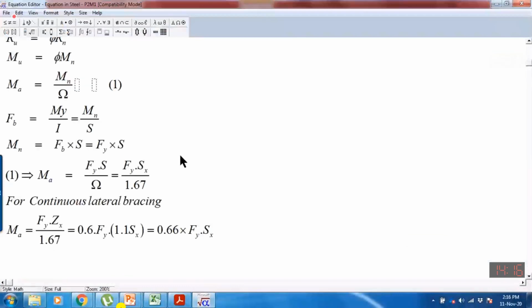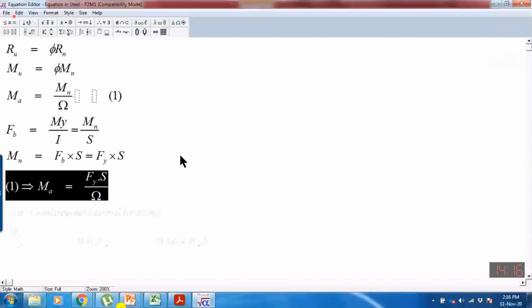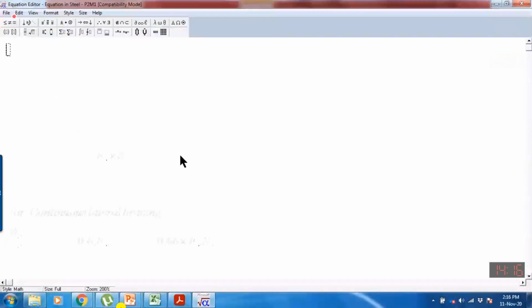I told you that after designing, we need to compute the total stresses in our section. If applied stresses are less than material strength, our design is okay. Total stresses, FB, I'm writing it here as FB, the total bending stresses in our beam in case of purlin, because this is subjected to biaxial bending moment.